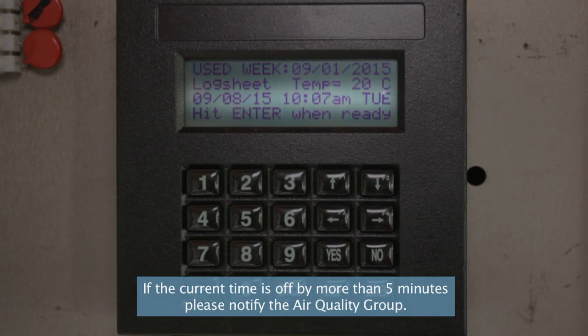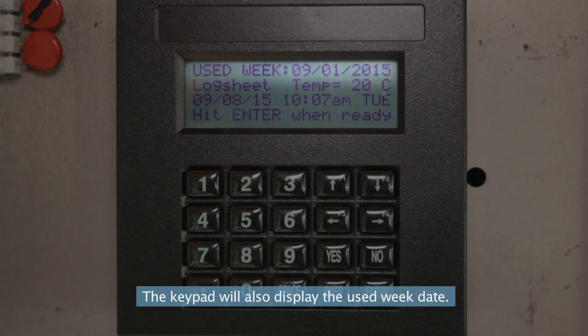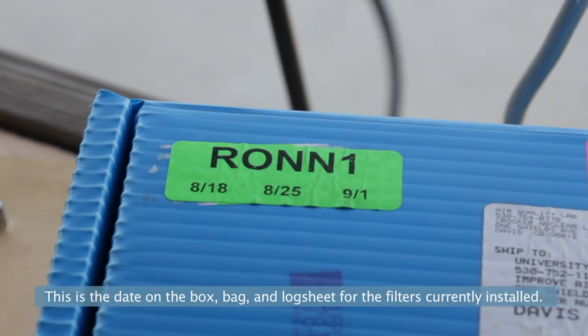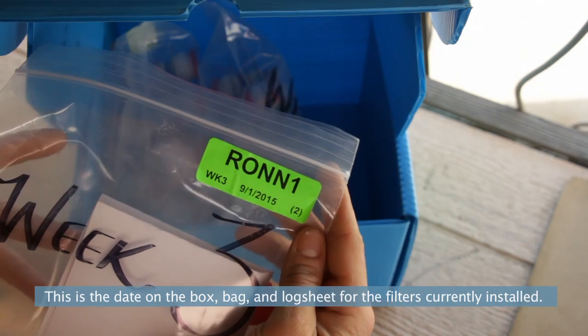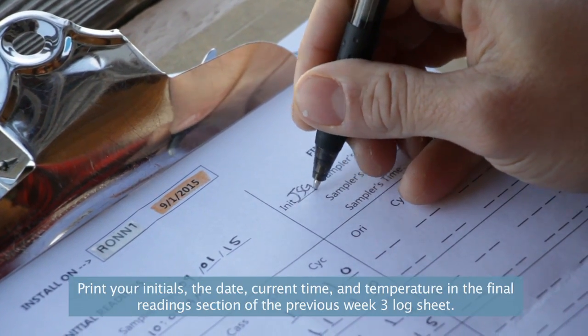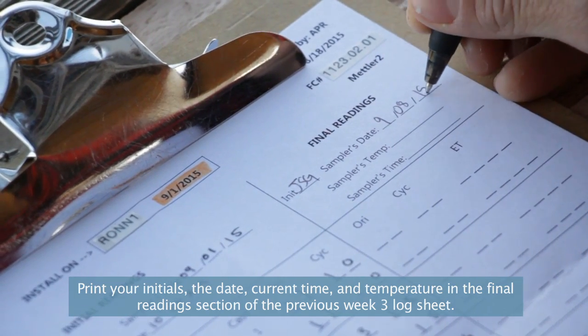If the current time is off by more than 5 minutes, please notify the air quality group. The keypad will also display the used week date. This is the date on the box, bag, and log sheet for the filters currently installed. Print your initials, the date, current time, and temperature in the final reading section of the previous week 3 log